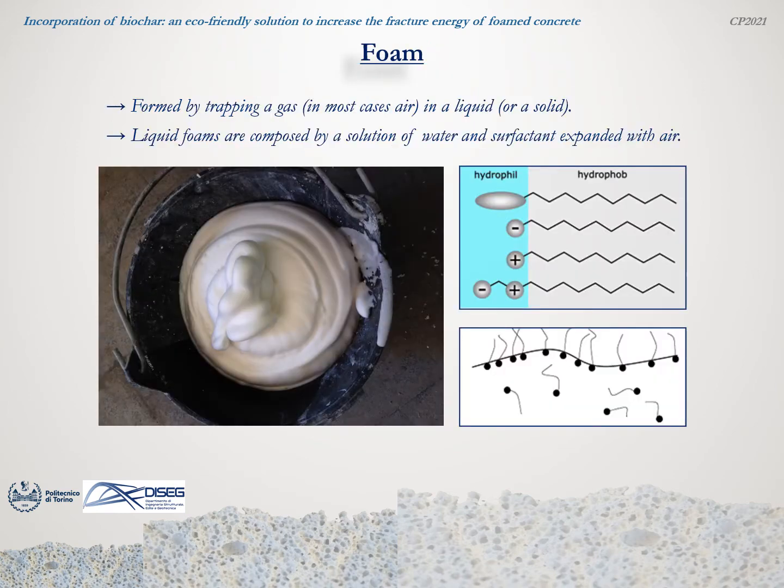Therefore, foam is the ingredient that characterizes these cementitious materials, and it's created by trapping pockets of air in a liquid phase in order to obtain so-called liquid foams. In general, liquid foams are composed of a solution of water and surfactant expanded with air.